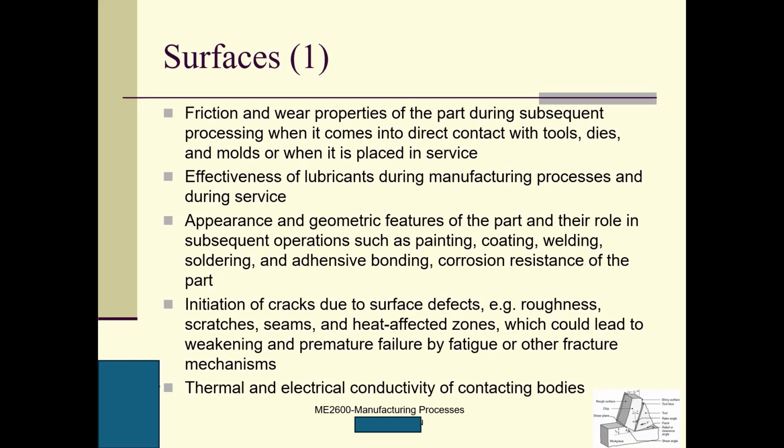So if you do not use coolant or minimum quantity lubrication, a lot of heat will be there, your tool will get warm very soon, and there is a very bad heat affected zone on the machined surface. It's very bad. So as a result, we need to have coolant.